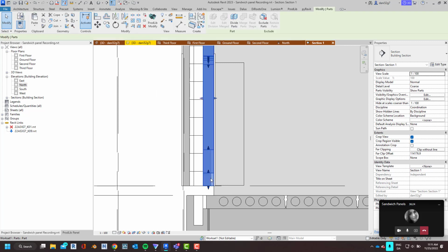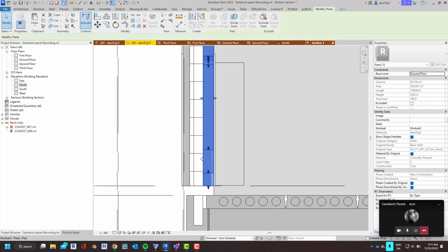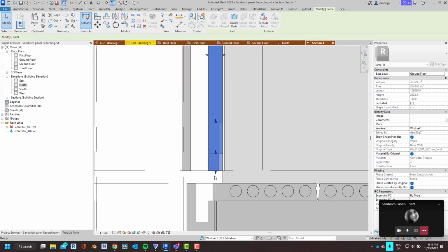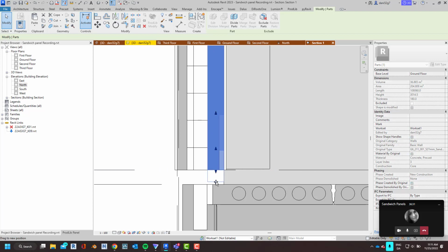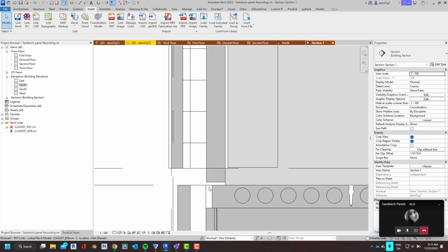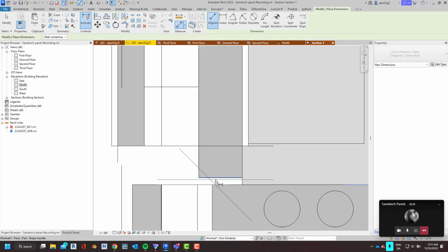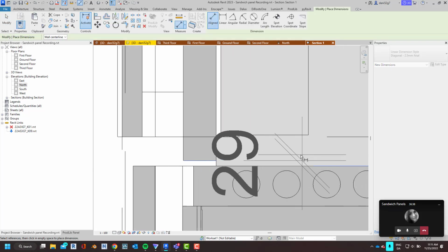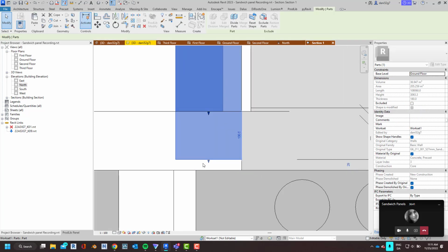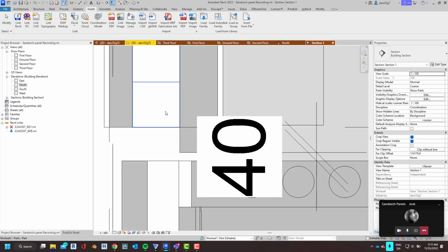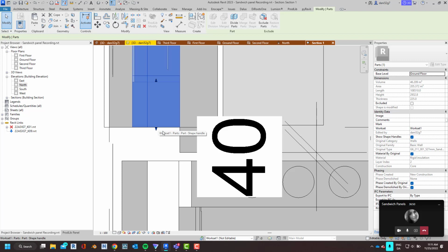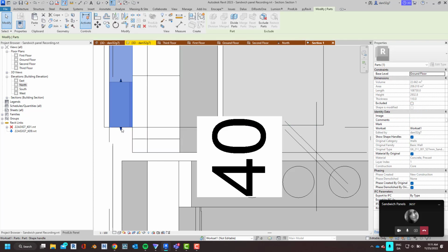So why did we do this? Because before we split them vertically, we can split them horizontally, or we can start controlling the settings already. So for example, we know we want to have 40 mils between the hollow cores and this in order to fill it with grout. So we're going to drag this to 40. And you can start controlling the horizontal parameters. The insulation, I can imagine, will go down perhaps to the same level, and we'll fill this in with some other insulation.